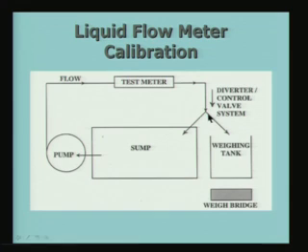What we do is we start the measurement process by allowing the flow to come to the weighing tank, and after a certain length of time you stop it and divert it back to the sump, and you find out how much liquid has been collected in the weighing tank, either by weighing it using a weigh bridge or by noting down the volume of the liquid collected. So, the volume divided by time will give you the flow rate, and the test meter will indicate whatever, maybe a delta P or some other signal, a voltage signal. So, you can see that there is a correspondence between the value indicated by the meter and the weighing tank measurement system. So, this is one way of calibration.